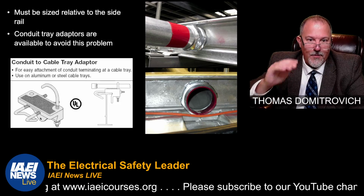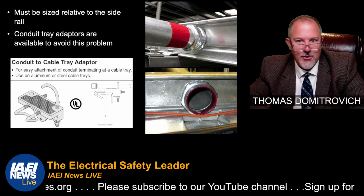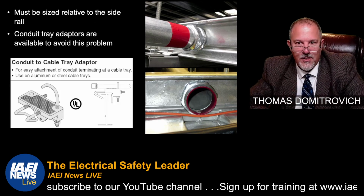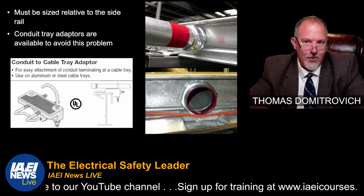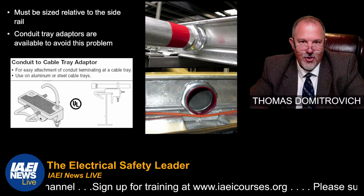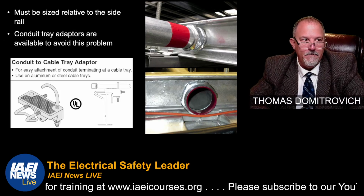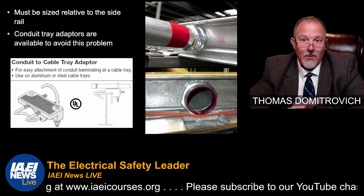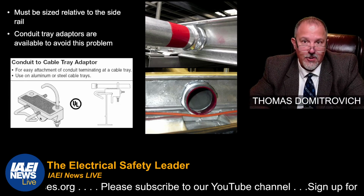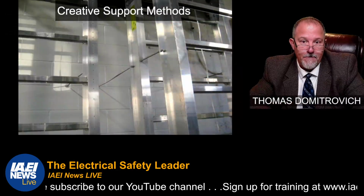And you probably want to come in over the top and dump into the cable tray, right? So follow manufacturer's instructions. Anytime you start cutting holes in equipment, I don't care if it's busway, cable tray, panel boards, switchboards, anything you start cutting holes into, you better have manufacturer's instructions to support the activity that you're doing.